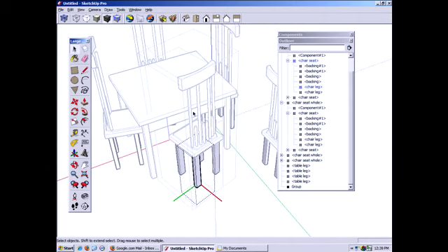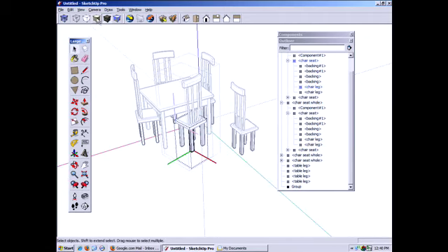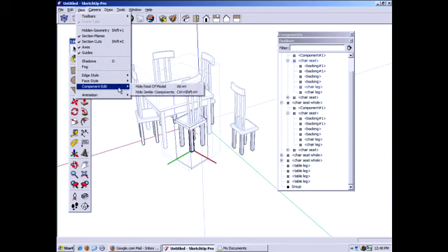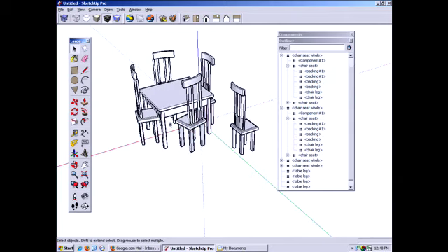Very handy to have. So the quick introduction, that's what it is. It's under the View, Component Edit, Hide Rest, and Hide Similar. And whatever shortcuts work for you, I'd actually recommend putting those into shortcuts to make it quicker.